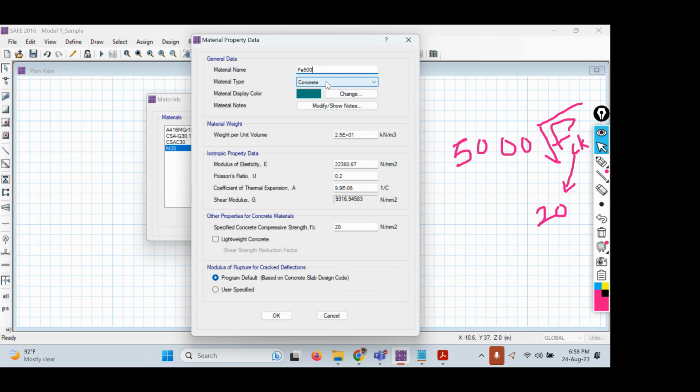Here, most of the people will get confused because here you can see two options. One is steel, other one is rebar. Tendon, it's okay because that is used in pre-stressed concrete. But which one we have to give? Is it the steel or is it the rebar? We should not give it as a steel. The reason is steel represents steel structures. That means when you are designing steel structures like a truss or a rafter or a gantry girder or a simple I section, all those are steel members. So when you are designing a reinforced concrete, they are all reinforcement bars. That is rebars. So don't confuse between steel and rebar.